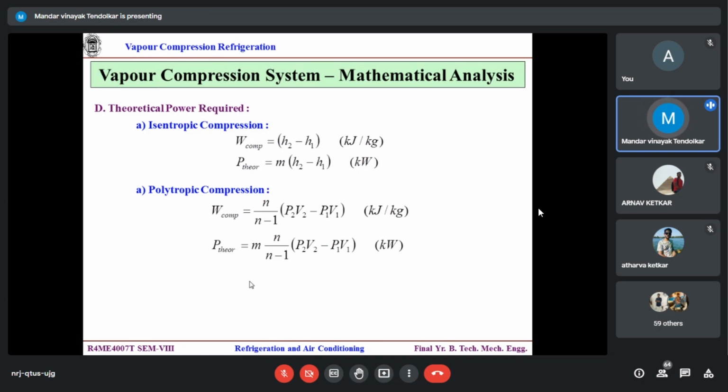I can find the specific volume from the density line. So take the specific volume at the inlet condition. Let's say density at the inlet condition is given, take its reciprocal, that is the specific volume, and multiply by the mass, which you can calculate from here. So that will give me the total displacement of the piston.